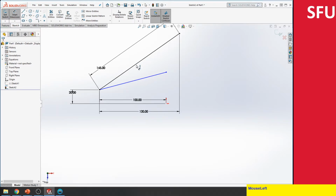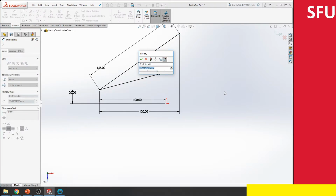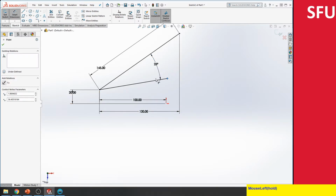So we are doing the smart dimension. For this, I would select the first line. So it says maybe it thinks you want to probably do a line. Now if I select the second line, it converts that to an angle. Now if I click, it gives me the option of changing the angle. Because I've fixed the first line, if I change this angle, the only thing that I can change is the orientation of the second line. So if I maybe made this 25 degrees, the second line reorients itself to here. And then now I can potentially change some aspects of this line. The only thing I can change is the length.